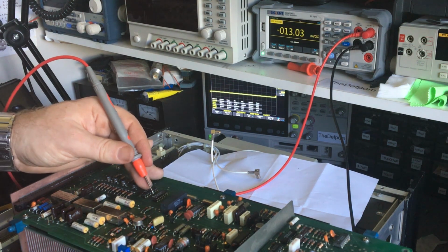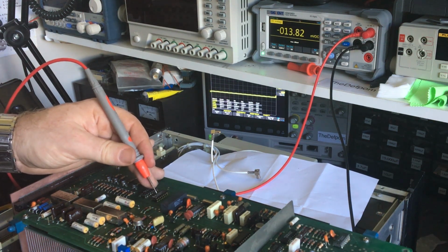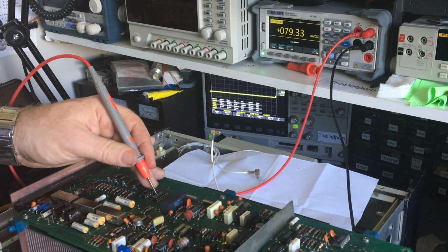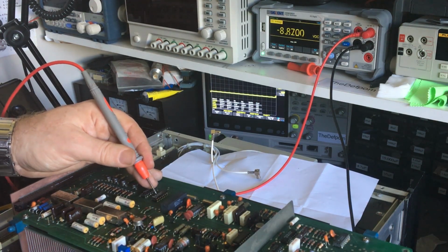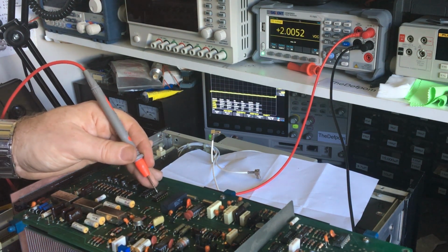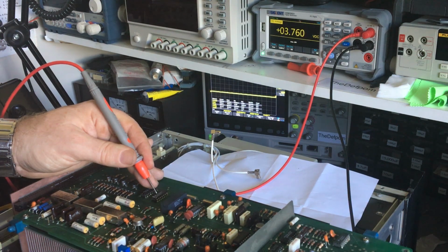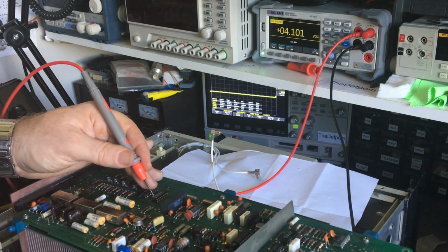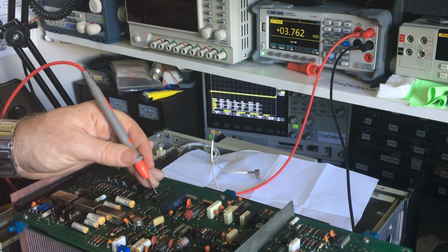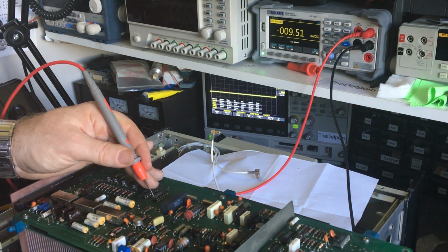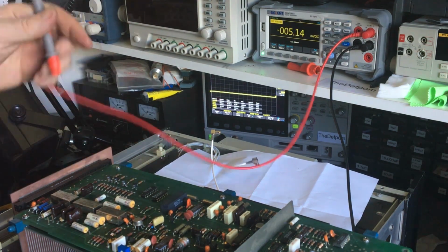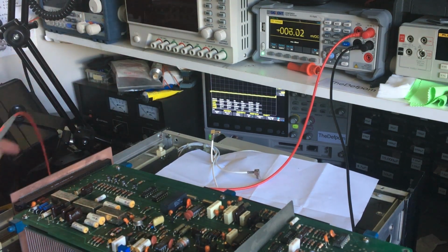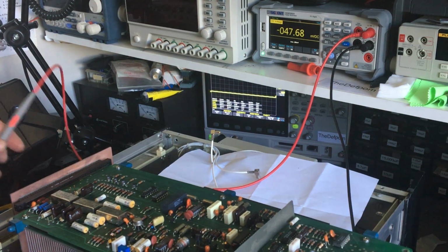So now I should just check the output, which is pin 11. That's off, so that means that should be high, correct. That's off, so it should be high and high, correct. That's on, so one of them should be low, correct. That's high, so one of them should be low still, correct. And that should still be high, that's correct. So U4 is definitely okay, and the inputs are definitely okay.